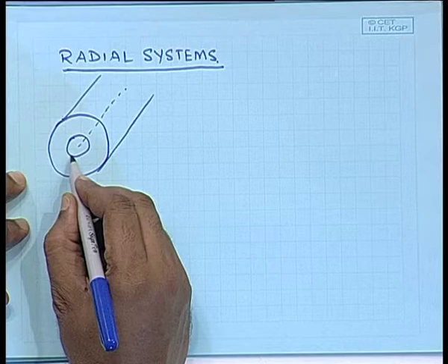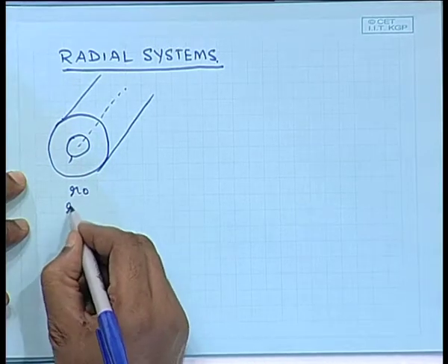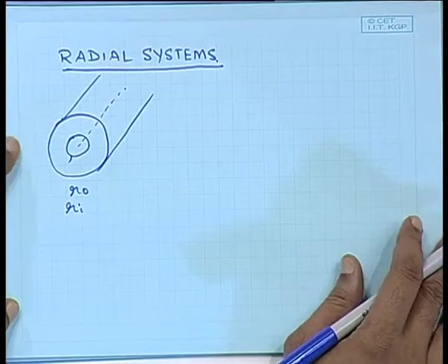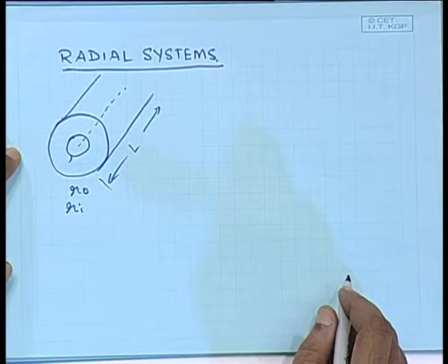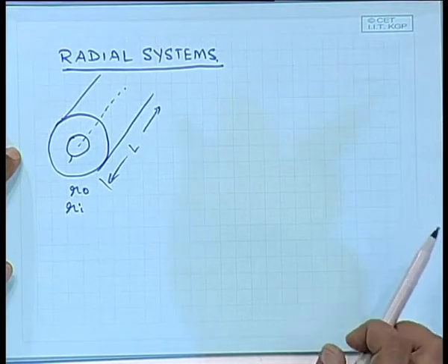The two radii are ri and r0, specifying the inner radius and outer radius, and let us say the length of this is L. It is a steady state one dimensional conduction in the r direction. So, I can simply take the heat diffusion equation in cylindrical coordinates and cancel out the del T del z and del T del theta terms. It is only del T del r which is going to be important. So, the variation of T with z and theta terms can be neglected.